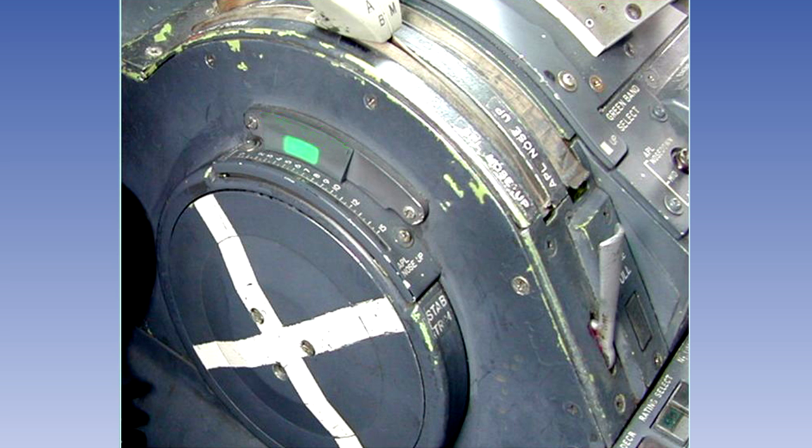The amount of trim required will depend on the centre of gravity position. In order to ensure that the aircraft will be trimmed in pitch on takeoff, recommended takeoff stabilizer settings based on aircraft weight and centre of gravity position will be given in the aircraft flight manual. The acceptable takeoff range for the stabilizer setting will normally be shown on the stabilizer trim indicator by a green band.